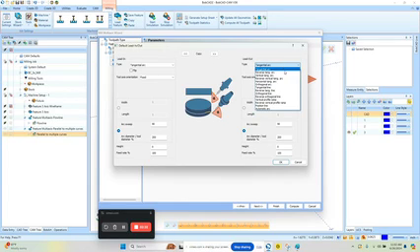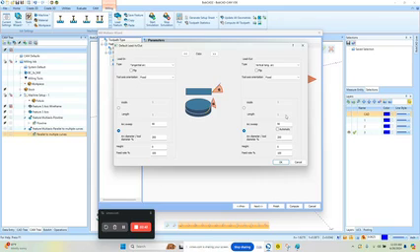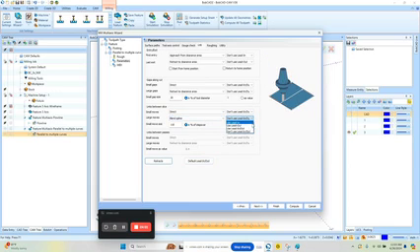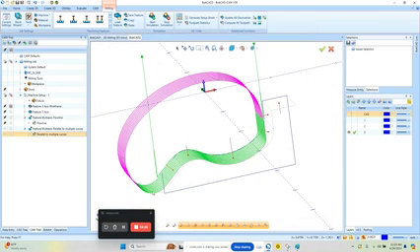But in the lead out here, I want this to be a vertical tangent arc, and then this is going to be 0.25, 0.25. Okay, so we add a lead out, and then for our large gaps we're going to say use lead out and then recompute. Alright, and you can see that lead out radius is now driving where this link back position is going to be.